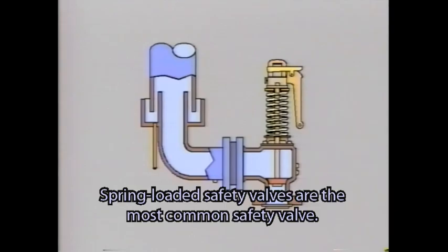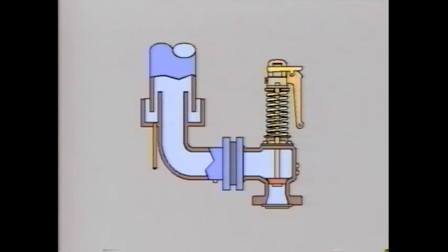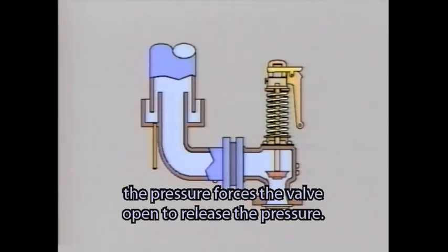Spring-loaded safety valves are the most common safety valve. A spring exerts pressure on the valve against the valve seat to keep the valve closed. When pressure inside the boiler exceeds the set popping pressure, the pressure forces the valve open to release the pressure.